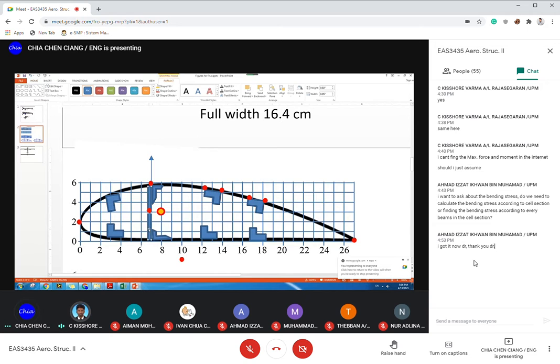For the first section, I already calculated the Ixx of the whole section, which includes this spar web. So for the second section, the other 3 sides must also include the spar web from the first one, because the spar web of the first section and the second section is connected. So does the Ixx calculation of this spar web in the second section include it?